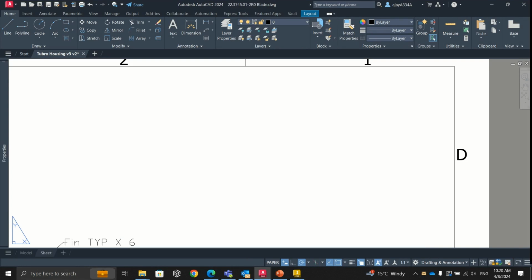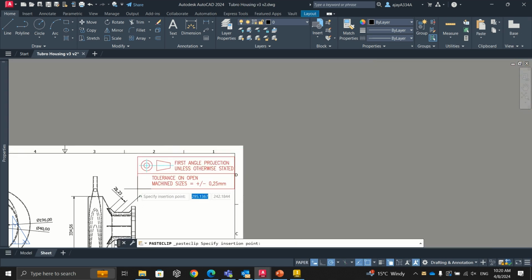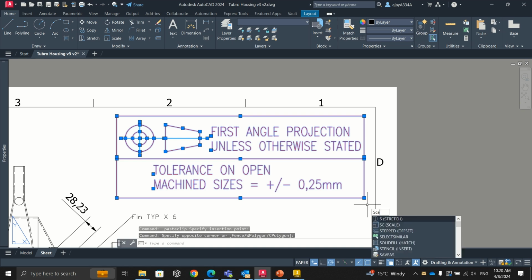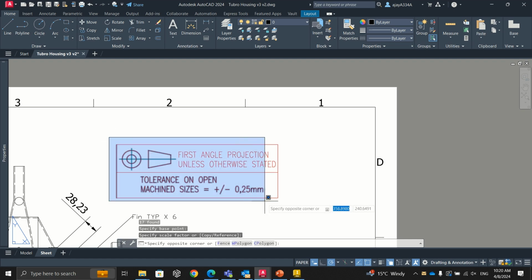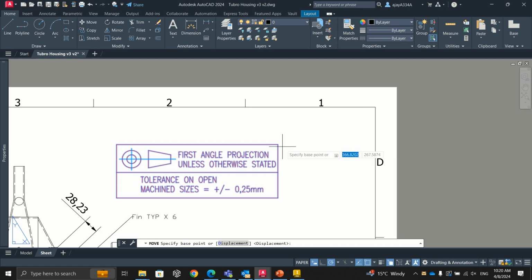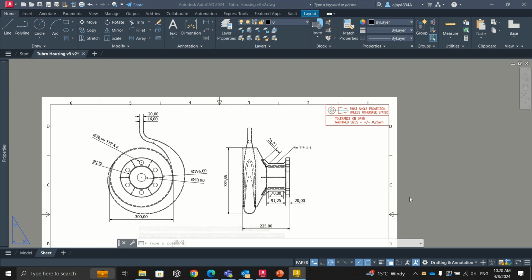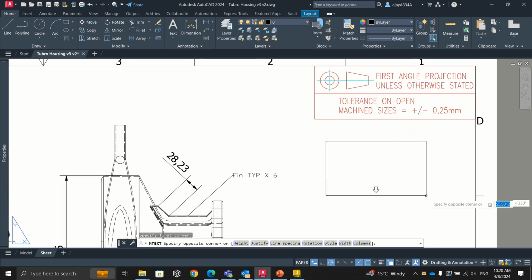For the designer to be able to transmit information, that information needs to be put on the page that's being sent out as well. So once your title block has been created, you've put your nice little logo in, you've got all the data filled in, who the engineer is, date of creation, the IP information, who's approving it, all of that information that's needed for controlling of the drawing and for your audit purposes, revision control, all of that has to happen in this particular drawing page. And in that drawing page, along with all of that, is machining notes.